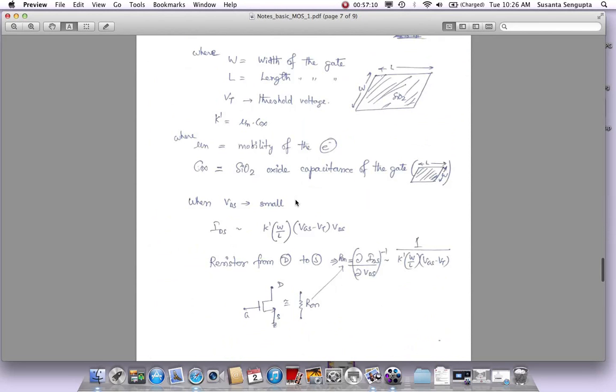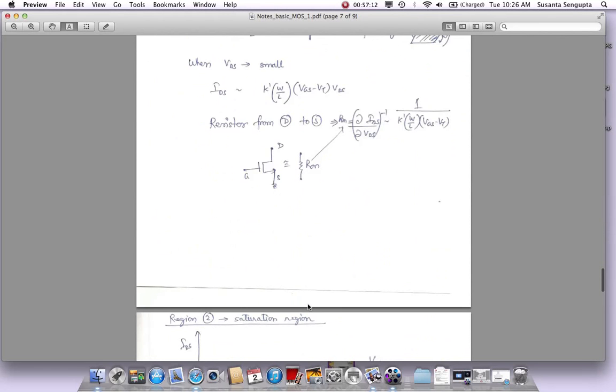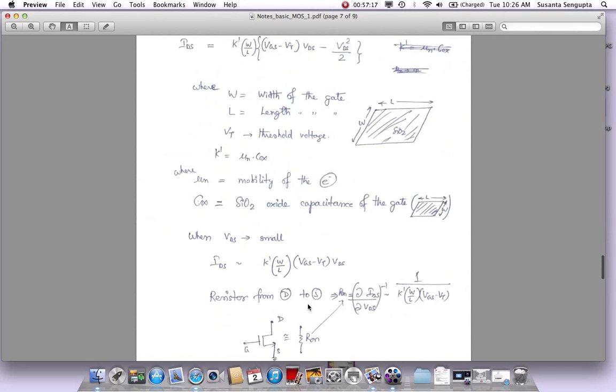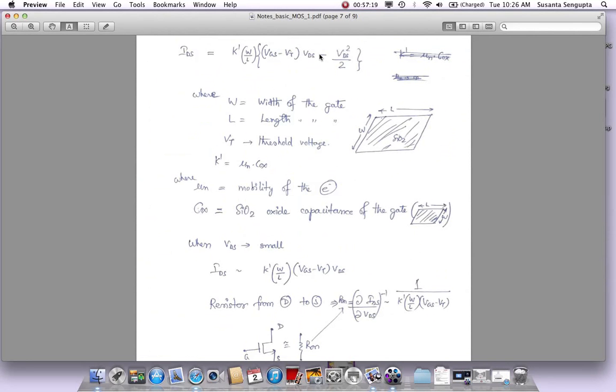Okay, so here's the drain current and the approximate value of the resistance that you can use, because in all these designs, you will use first order equations like this, and you will use these simple formulas to come up with a design. Like what should be my VGS if I know my VT, and what should be the W over L values if I know the mobility and Cox values. So all that will help you do a first order design on paper.